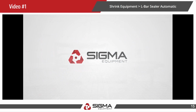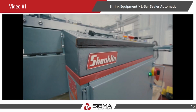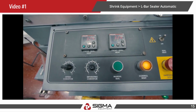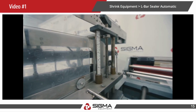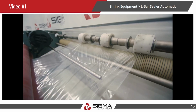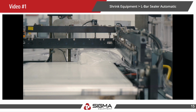Welcome to Sigma Equipment. Today's cycle test includes a Shanklin A27A automatic L-bar sealer. This particular machine is operating on a 240 volt system, single phase. It is capable of running 35 packages per minute depending on product size. The width and height are adjustable to fit different sized product. This specific machine is using clear film. Before the film reaches the inverter, it can run through perforated rollers, perforators to puncture small holes in the film. This will allow the air to vent when the product is going through the heat tunnel.